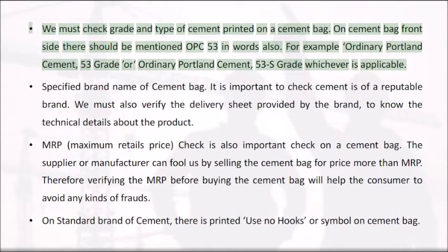We must check the grade and type of cement printed on a cement bag. On the cement bag front side, OPC 53 should be mentioned in words also. For example, Ordinary Portland Cement 53 grade, or Ordinary Portland Cement 53S grade, whichever is applicable.